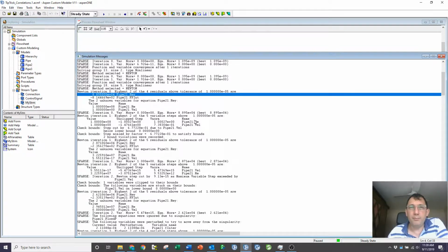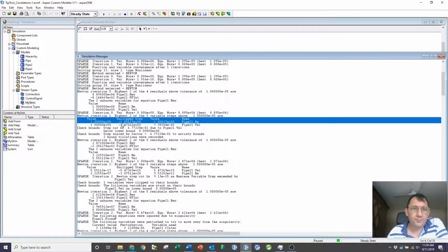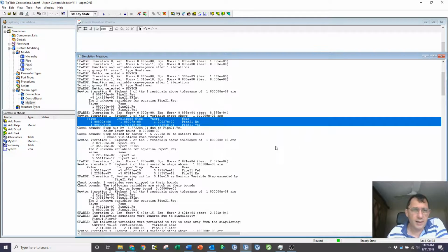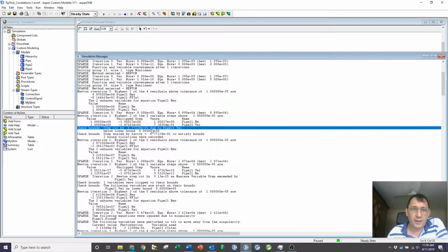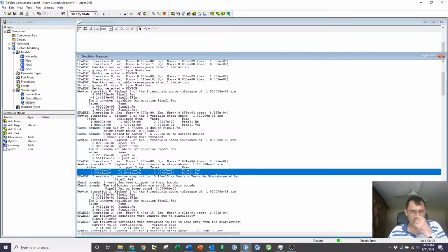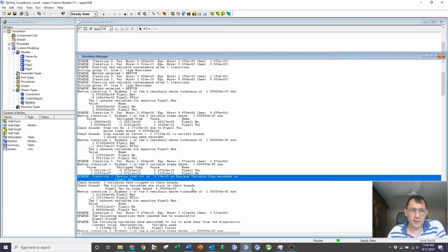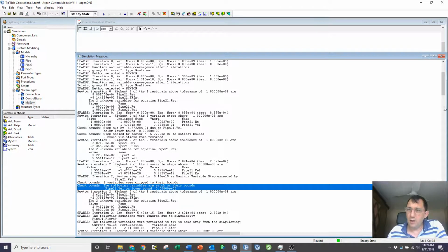It's a relatively large pressure drop, so I'm going to anticipate having a large flow, so my Reynolds number is going to go up a lot. Interestingly though, it's trying to push my Reynolds number negative and it's trying to push my velocity negative. That's a bit troubling. It doesn't let them go negative, so it's going to prevent it taking a full Newton step. And so then at my next iteration, I'm going to again push that velocity and Reynolds number, and now I'm pushing down very negative. And again, that's a bit worrying. I've got stuff stuck on my lower bound.